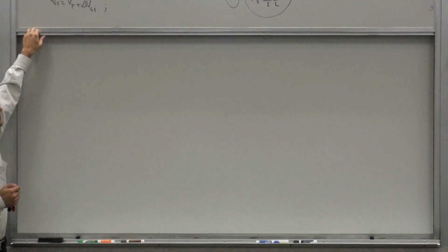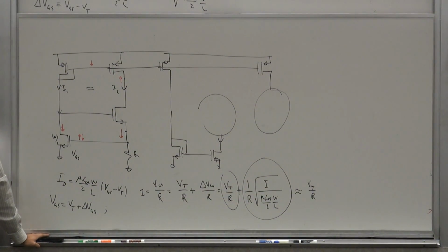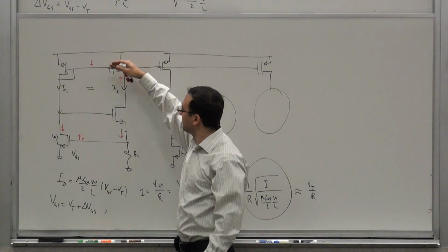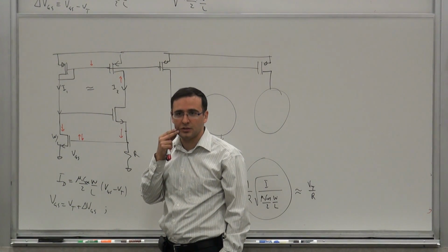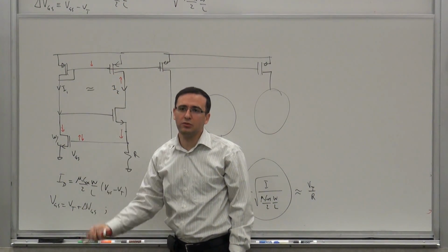If you want to use, yes. When you want, after you build this voltage supply independent current, and then you want to mirror it, or in the mirroring part, you still have the effect of supply because the VDS of that PMOS transistor appears in there. So you have the effect of supply even here. You don't even need to get there. If you don't ignore the channel length modulation, the output resistance of the transistor, even if you change the supply, you see some effect here. You've just reduced that effect.